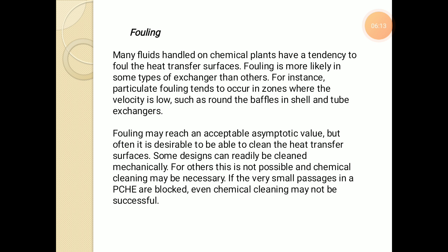The next important factor is fouling factor. As I earlier mentioned, generally we need to use river water or sea water in a condenser or in a cooling tower. When that salty water flows over a coil or over metal, it forms scaling. It deposits over that material, and because of that, extra thermal resistance has to be added which resists heat transfer.